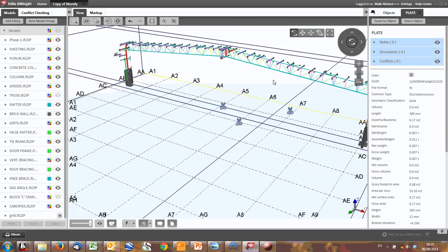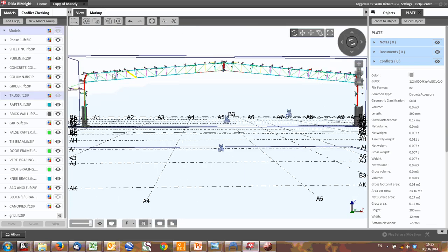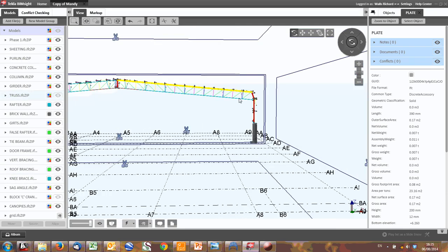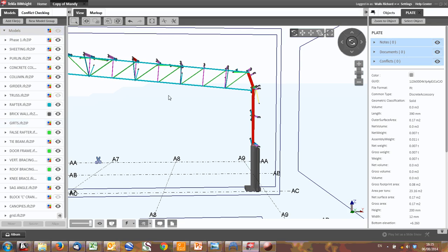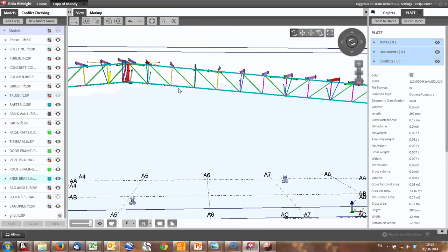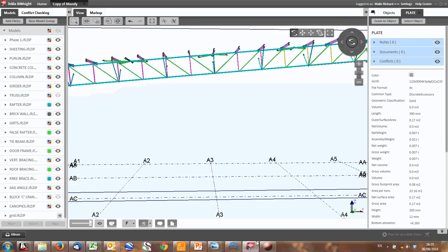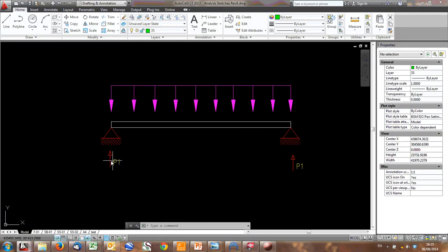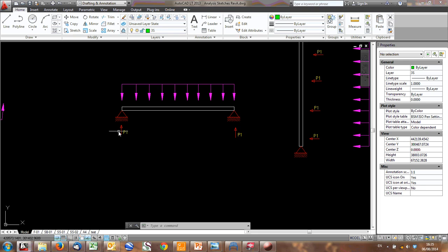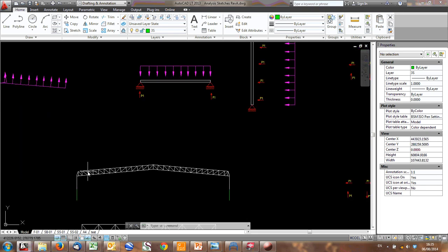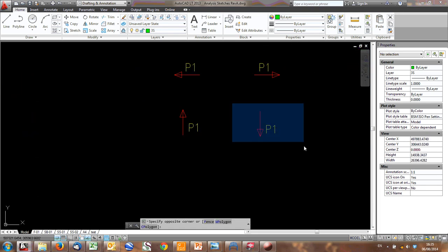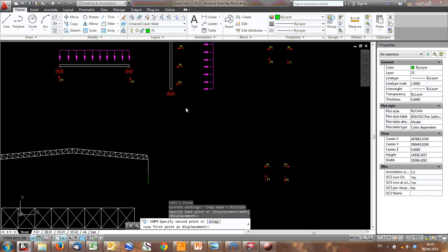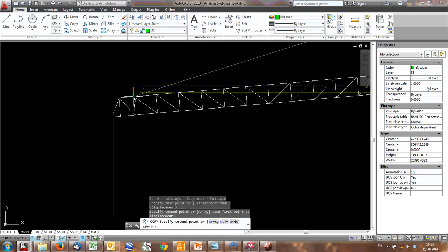Okay. So all these trusses that sit all these purlins that sit on top of the truss. Purlin, purlin, purlin, and all down. And here you've got the girts. And those are supported by this truss. So if you have a look at this truss, let's go back here. If you get this reaction now could actually be applied to this truss. So let's go put that on here. And this now comes down in all these different loads.